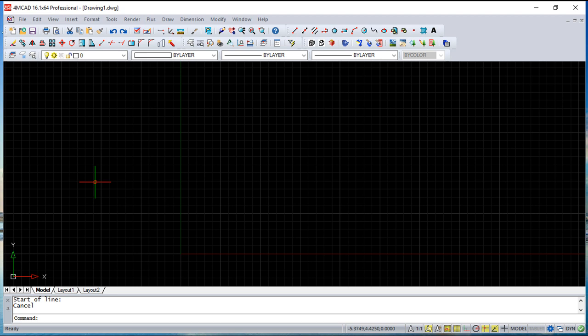More or less the same way, there are other possibilities with these repeating commands. You can press Control K and go back through the commands, and when you stop on the command you want, you just press enter to confirm. Or for example, you can also use the up and down arrows of your keyboard, and you will go through the commands that were done. It's another possibility.